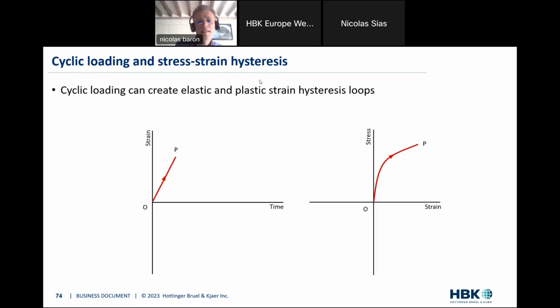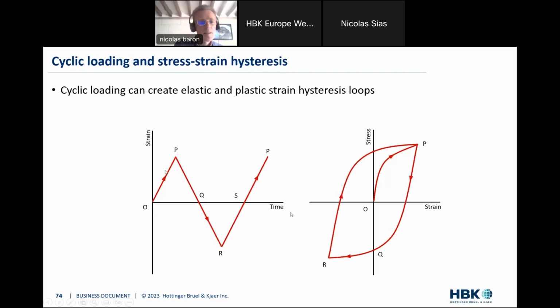It's this, and you might have seen those before in the past. What do we mean with hysteresis loops? It simply means that when we start loading and unloading the component, we'll have such curves in the stress-strain plane. We have these loops here, and typically they are called hysteresis loops because the material has some memory. So after some initial stabilization phase, the curves will just repeat themselves. You need a couple of cycles for that to happen, but after a while, the curves really stabilize, and the hysteresis loops manifest themselves very clearly, such as this one here.